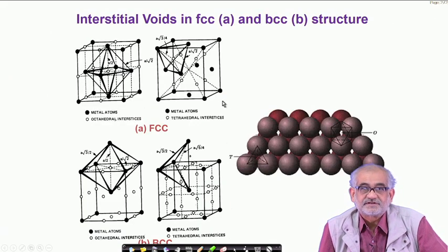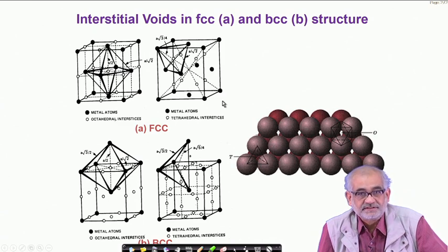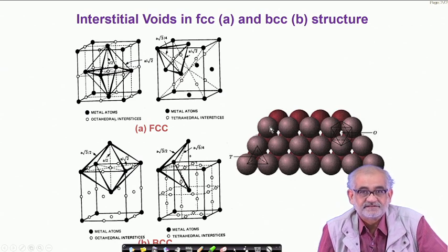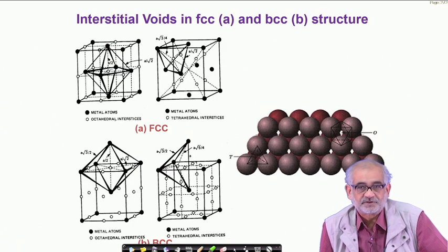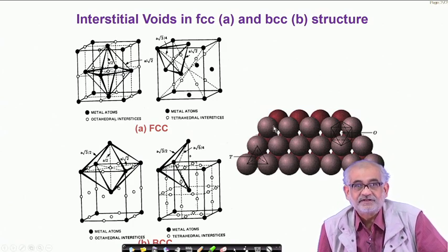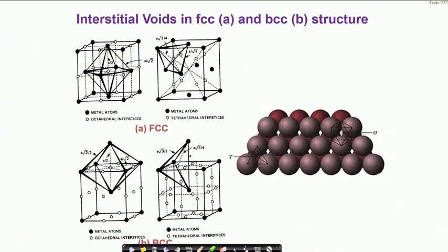While talking about crystal structures, we are talking about specific locations of atoms, and for simplicity we assume that atoms are hard spheres. We all know that we cannot fill up a box, no matter what the size or shape, completely 100% with solid spheres. So there will be certain open spaces left, and that allows us to create the concept of packing density.